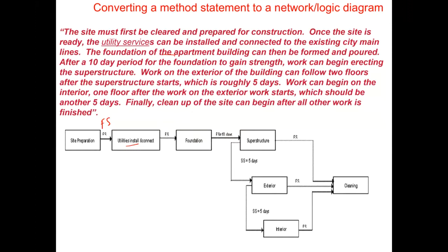However, as we continue reading the problem description, it states that after a 10-day period for the foundation to gain strength, work can begin erecting the superstructure. So basically, after the foundation, we have to wait for 10 days for the concrete to gain strength, and then we could begin work on the superstructure. Mind you, this is a relationship of a finish to start with a lag of 10 days.